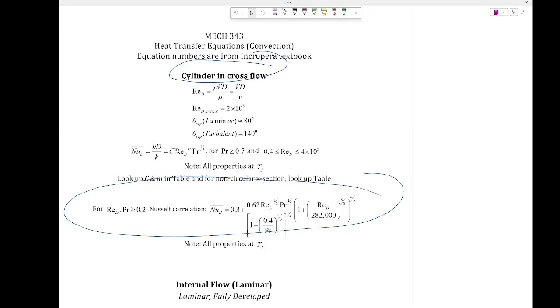Now, in external flow, you still remember we had the length of the plate, right? That's the external flow thing. For flow around the cylinder, it's not important how long the cylinder is, because the flow is coming across the cylinder, right? So what is important? The diameter of the cylinder. I'm assuming that my hand is a cylinder. Does it make sense? So the diameter of my hand. When you find the Reynolds number, you're going to use the diameter of the hand. Everybody understand this? Okay, that's flow around the cylinder.